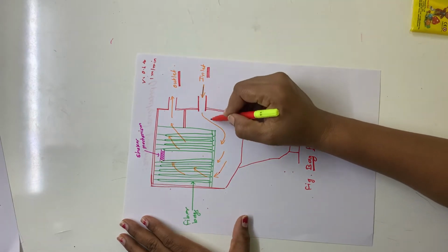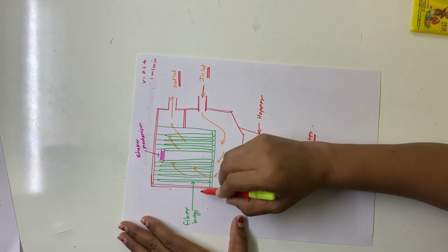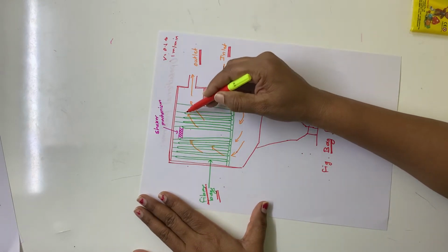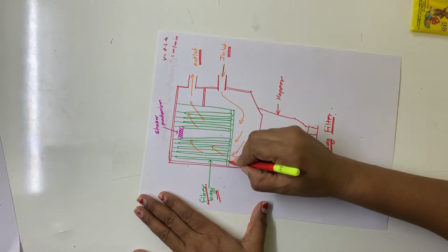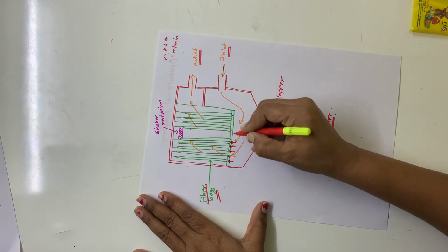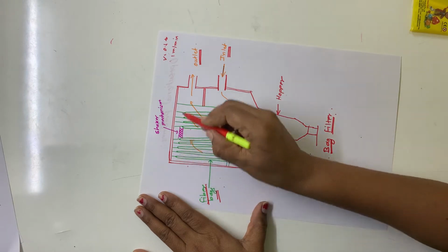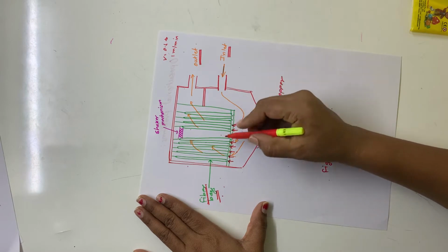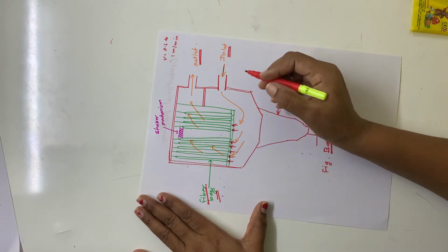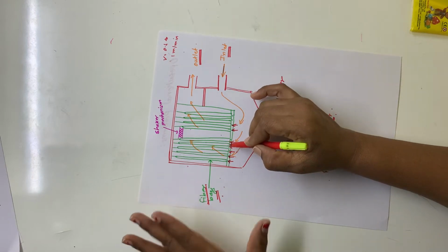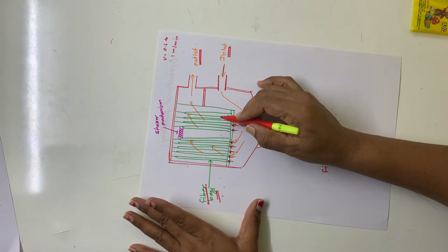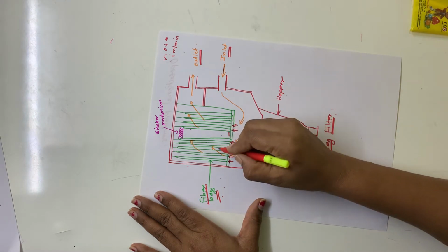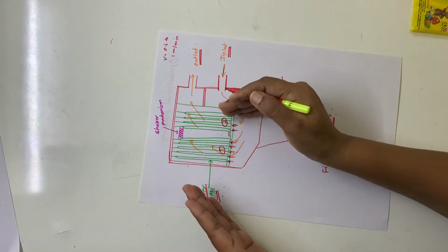The gas comes through the inlet chamber, and here a number of fiber bags are arranged in a reverse manner, vertically in a hanging position. Its open end is at the bottom and the closed end is at the top. Such fabric bags can be inserted in a hanging position in a bag filter for the control of air pollution. Numerous bags can be added, and you can make different compartments the way I have shown here. This is one compartment and this is the second compartment. Many compartments can be used.